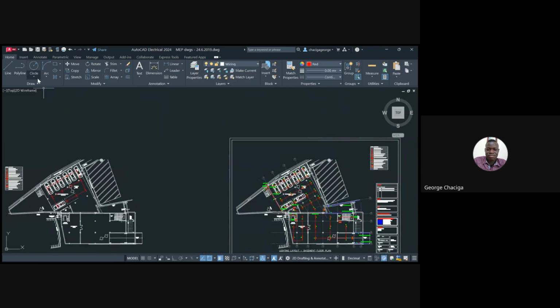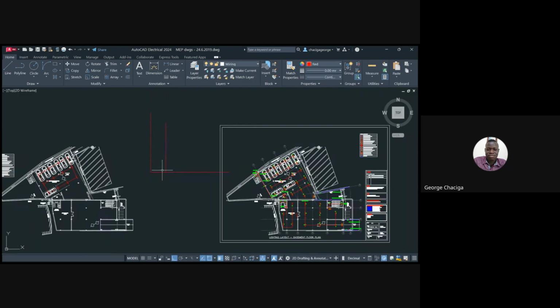What do I mean by inrush current? Let me demonstrate it here. As you switch on these lights at the start, you can see from this graph, the current at the start shoots. In just some microseconds, very small seconds, it would shoot high the moment you switch on that circuit of light. Then, with time, it goes low.